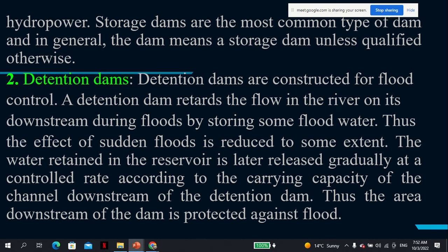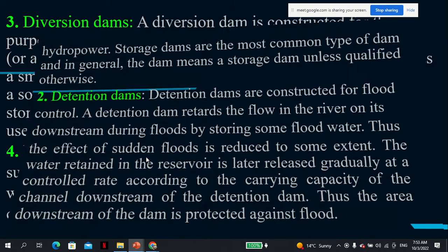Of a lady from Nyakach saying it was the government's idea, because every time it was raining, floods used to happen. So you can do a detention dam, because during the rain there is excess water in the river. Of course there are other measures that can be taken. For example, you can dredge the river, because there are probably deposits of alluvial in the river. So when more water comes, it overwhelms, and it goes out of the channel of the river. Apart from that, you can do a retention dam where excess water is contained and then released at a controlled rate, such that people's lives are not in danger.